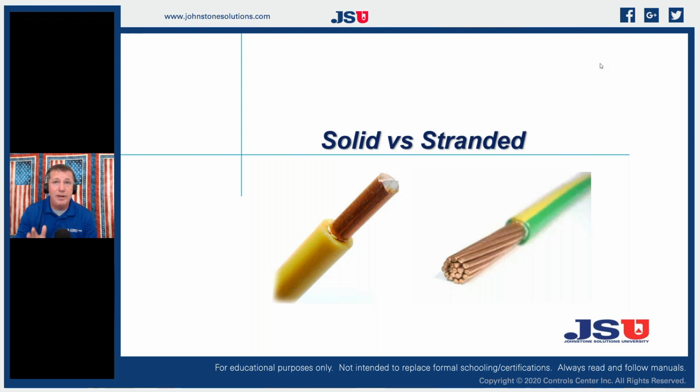As we start moving away from traditional legacy, and you're going to hear that term a lot in the industry, legacy. What legacy wiring would mean is that we're using a standard transformer with 24 volts AC. So legacy wire is going to be our common RYGW, where we're sending 24 volts across conductors to energize some type of a load, some type of a relay or a contactor or some type of a device. So we're doing work with our wires. And traditionally, we've always used solid wire to do that work with.